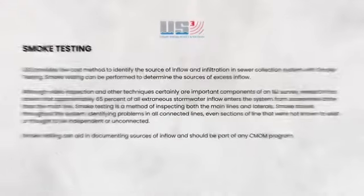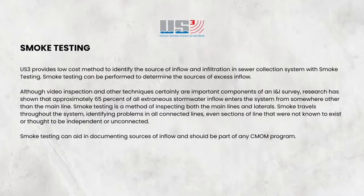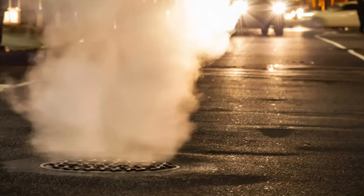Sometimes smoke testing is very popular, but sometimes you can literally just go through the neighborhood and look, and you'll find these problems. Go through meaning you'll see it if you just watch where water drains, for example surface drainage, or a downspout tied into a clean out. Absolutely, all of these. You do this enough. We do this absolutely every single day, 7 days a week, 24 hours.